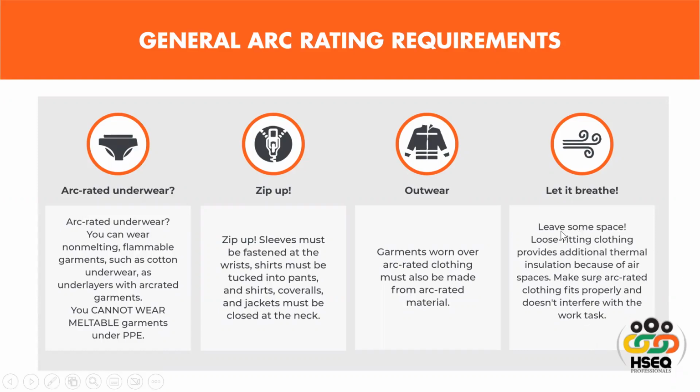Then, let it breathe, leave some space. Loose fitting clothing provides additional thermal insulation because of air space. Make sure arc rated clothing fits properly and does not interfere with the work task.